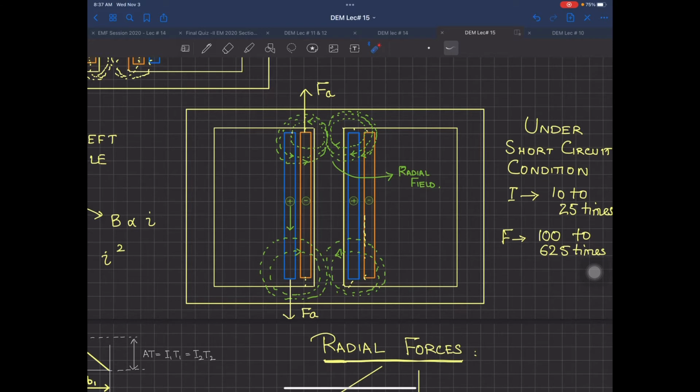The air gaps are compromised. So the winding will start moving. Once it moves from its location, it will start vibrating in normal conditions also. If a new transformer is there, you won't hear that hissing sound. Not from the corona discharges, I'm talking about the windings moving inside it.